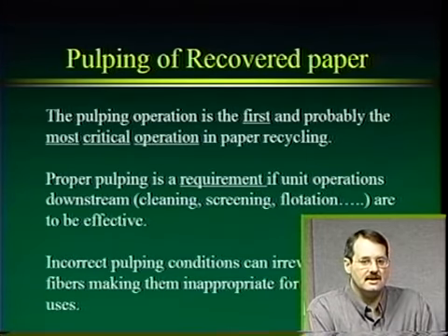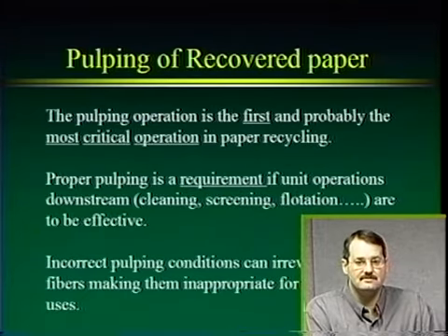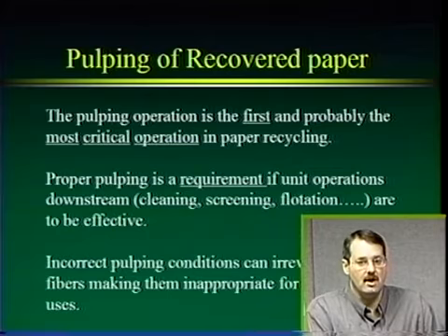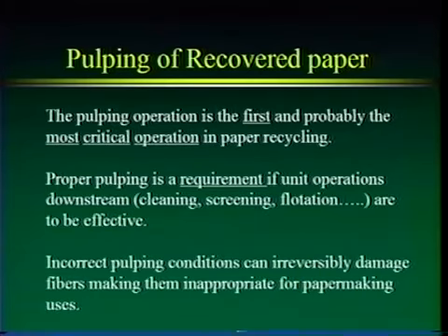The second thing is that if we incorrectly pulp, let's say we over pulp, a very bad thing can happen. We can actually destroy our fibers. We can cut the fibers, generate fines, and for that reason, we're going to have an inferior pulp material for paper making.